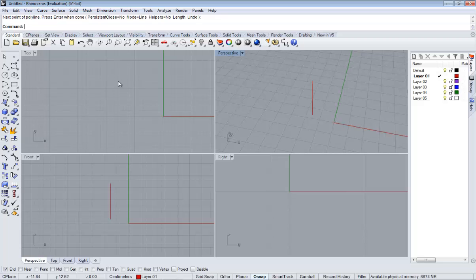Now we're gonna draw a circle, so click on circle, and we want to start that circle from that endpoint. To find that endpoint, we must check this option here, the first one. So center of circle, that point. And now we're asked for a diameter. A diameter could be, for instance, 15 centimeters also.